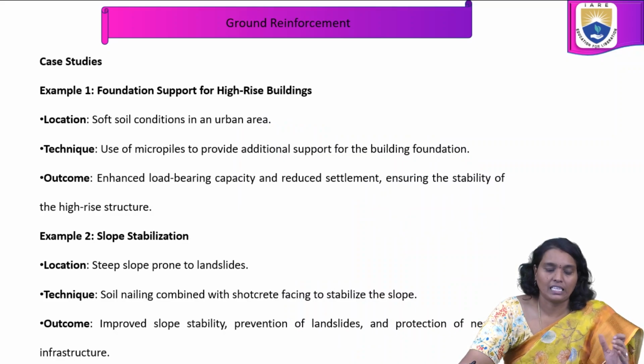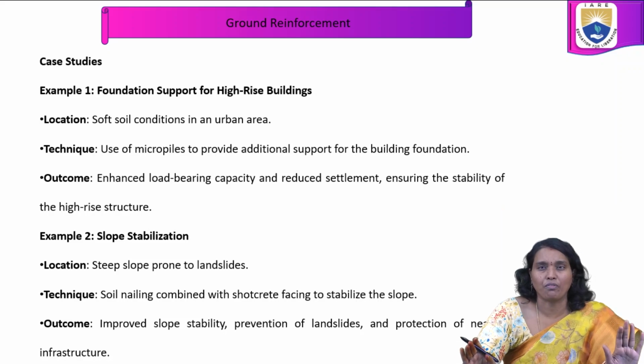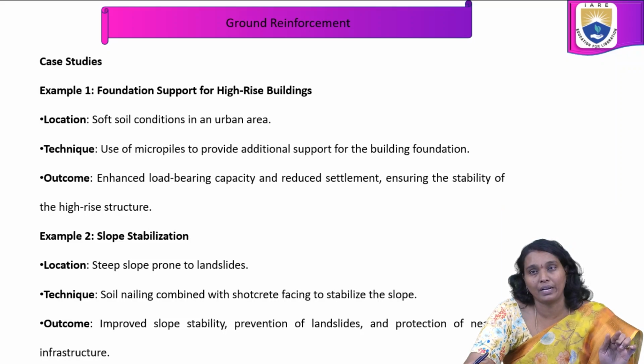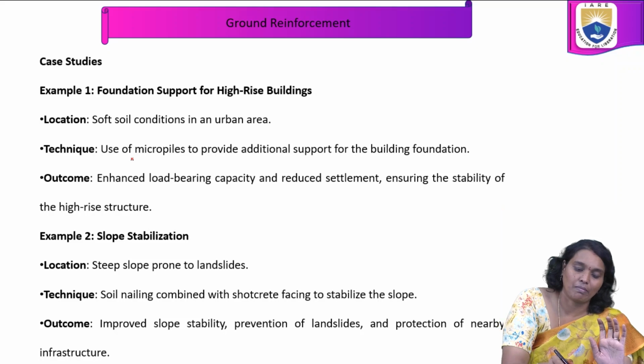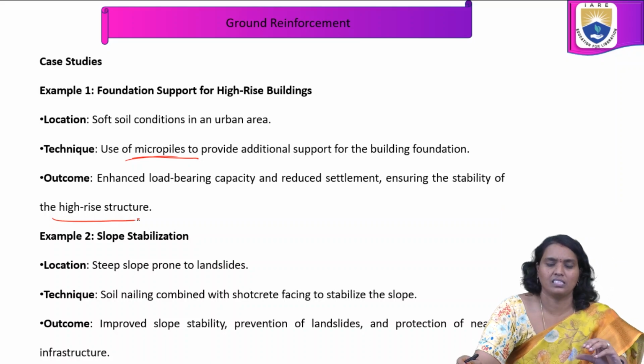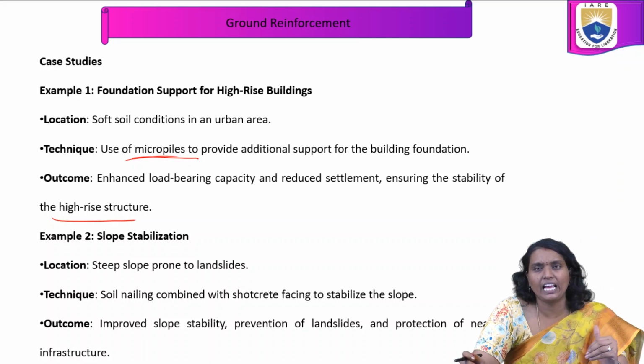For example, consider a case study: foundation support for high-rise buildings located in soft soil condition in an urban area. In that particular case study, we are going to choose micropiles to provide additional support for the building foundation. The technique is micropiles. The outcome is enhanced load bearing capacity and reduced settlement, and also ensuring the stability of the high-rise structure. This is one example. In detail also we are going to understand such examples.